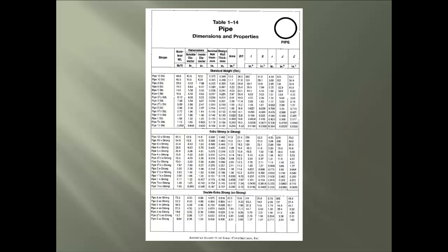We come to the table for pipe. First, the table provides a category chart that provides columns for the pipe diameters and schedules, but please notice the three different tables provided. The first covers a pipe for standard weight, then extra strong, and lastly double extra strong. So, as you review the mill certification of what you might think is a common piece of pipe, slow down and make sure it matches what you really have on the floor.